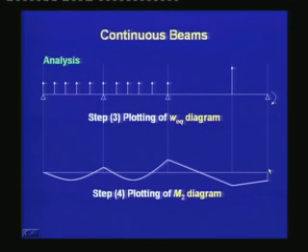From the V diagram, we can calculate the W equivalent diagram from the relationship W equivalent is equal to dV divided by dx. We have an upward load in the spans. Note that the downward loads at the supports need not be considered because they directly transmit through the supports to the ground.